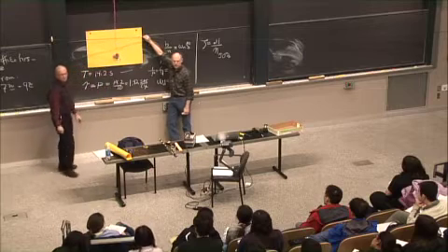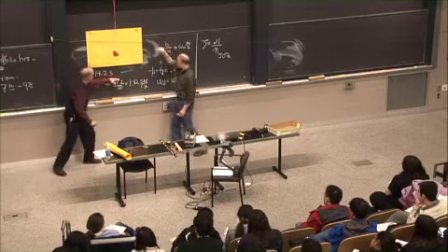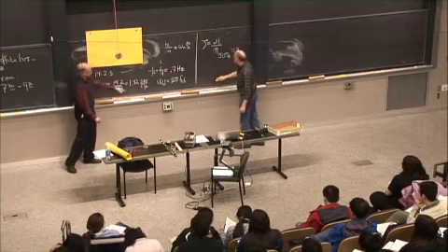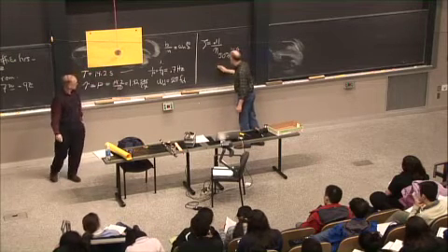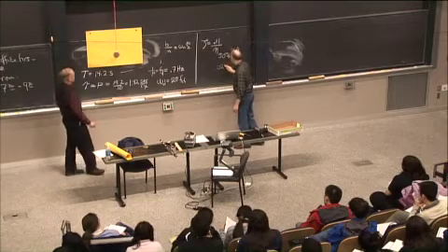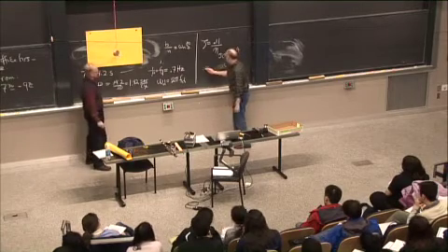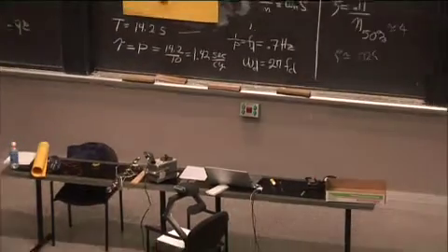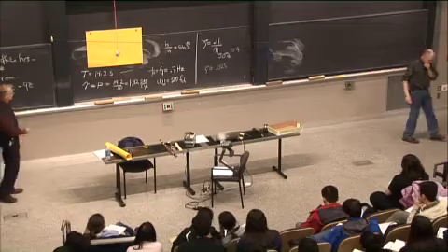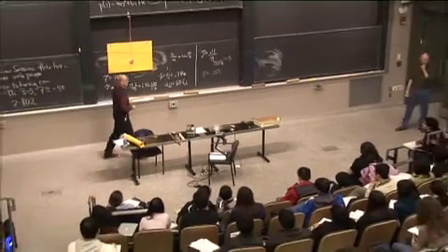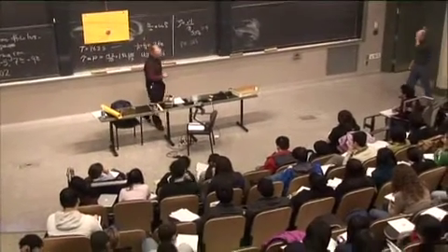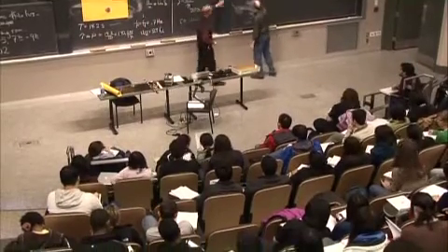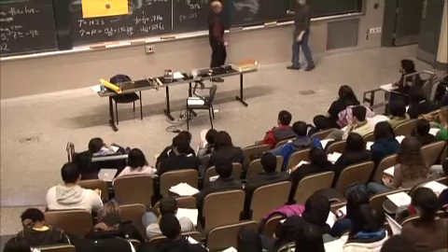About there. What do you think? About 4 cycles? It started here, and you only could get that far after 4 cycles. So it's about 0.11 divided by 4, about 0.026. Zeta is about 2.5%, an engineer would say 2.5% of critical damping. A quick way to measure it. So where did this 0.11 come from? Let me see if we can work this out mathematically. Don't pay any attention to this black rope.